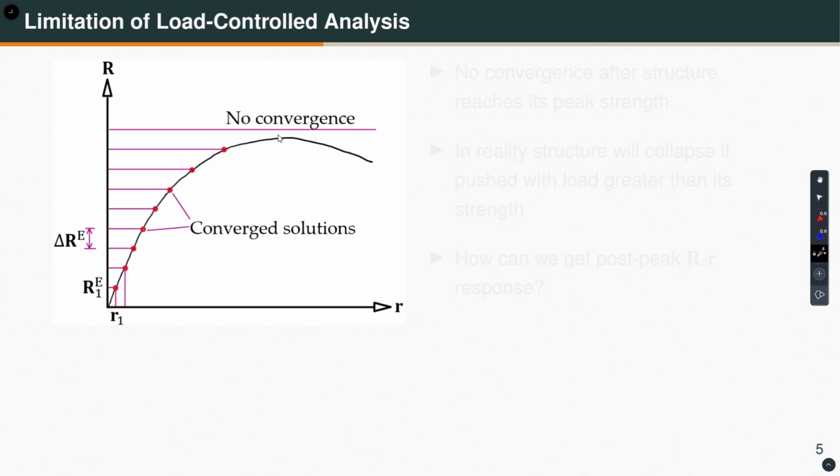But after that, if you ask your controller to increase the load, okay, what will happen? The actuator will keep pushing the specimen because it is trying to achieve that load. But the structural component which is offering resistance can never give that resistance because its strength is only this much. So, what will happen? The actuator will keep pushing the component of the system and eventually bring it down to collapse.